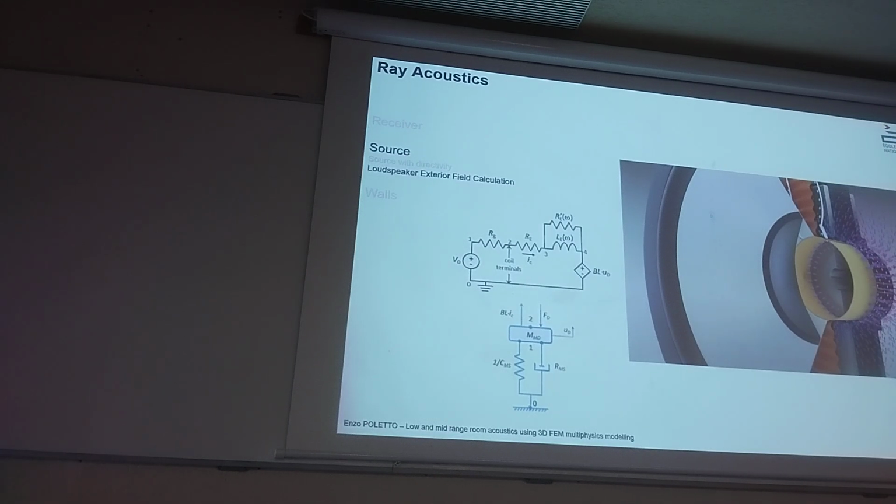The membrane has this little mass spring system, and basically when a magnetic field is created in a coil, it's going to translate that to the membrane that moves and recreates the sound wave. That's how a speaker sounds. So you get electromagnetism, mechanics, and acoustics. That's a free physics model. So I can do that as a multiphysics modeling, but I could simply do that with an equivalent circuit.